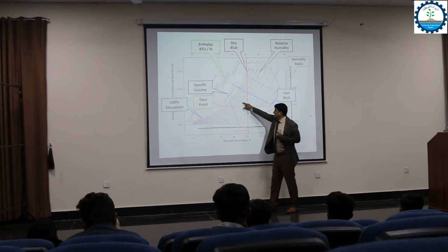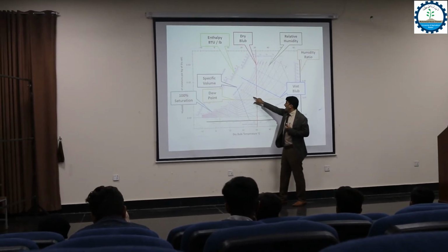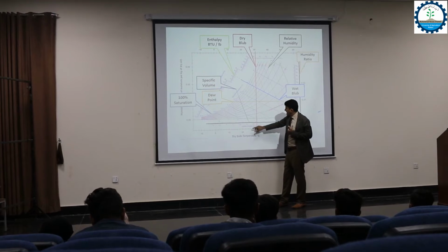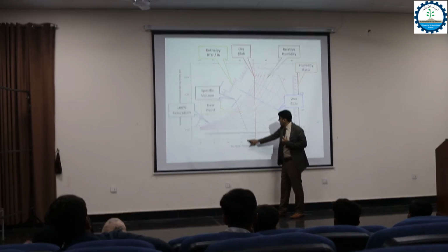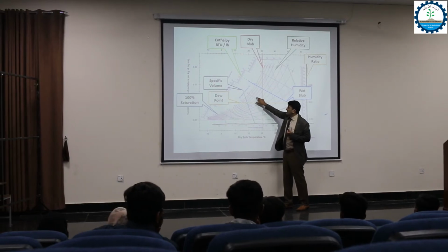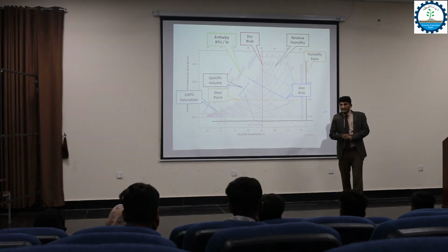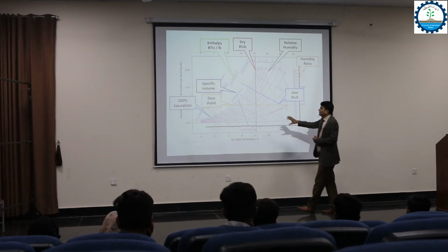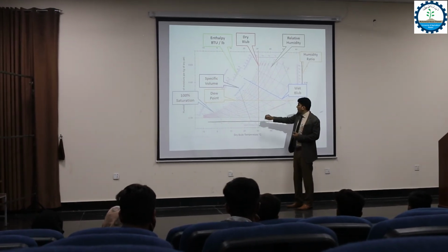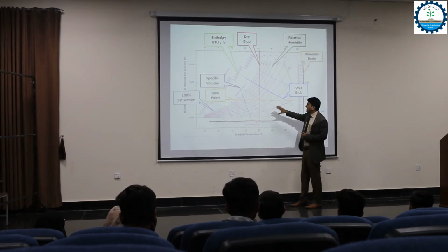Here are the blue wet bulb lines, 20 degrees Celsius. You have to follow this line, and here 25 dry bulb temperature, where they cross each other. This will be your main focus point, predicted from two given variables. When you find the one point, you can easily judge the other parameters.